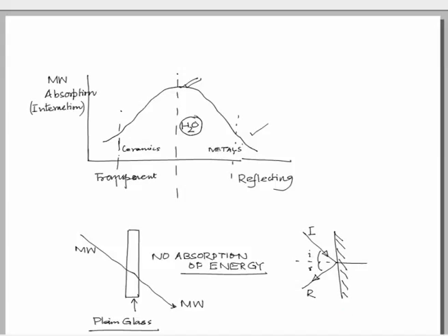That means, in this case also, if the material is totally reflecting, then there is no energy being absorbed for processing the material, or in turn for heating the material. Thus, there are challenges in processing these two kinds of materials which do not absorb microwave energy directly.